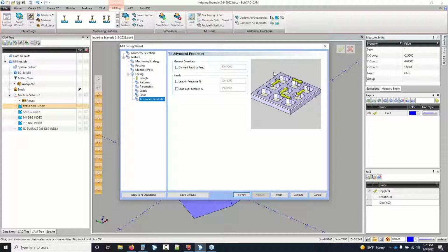Now, there's no specific machine that does it that I could say there's a specific version of it. But the guys that I've dealt with that have to deal with dogleg rapids are usually running Haas machines. Again, if you ever see your rapid moves doing a strange move in a weird kind of direction, instead of going straight to the corner they're supposed to go to, if they seem like they're kind of zigzagging out of the way, you'll want to take note of that. Even then, it usually doesn't cause a problem unless you have some sort of fixture or something that the tool can run into.